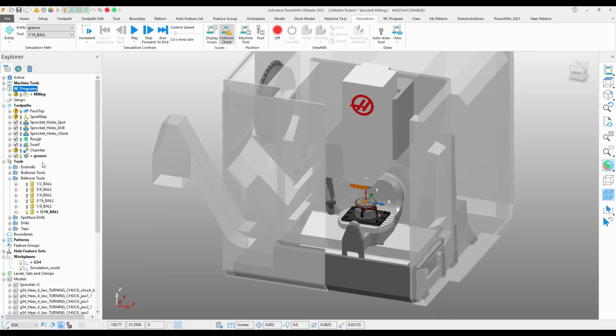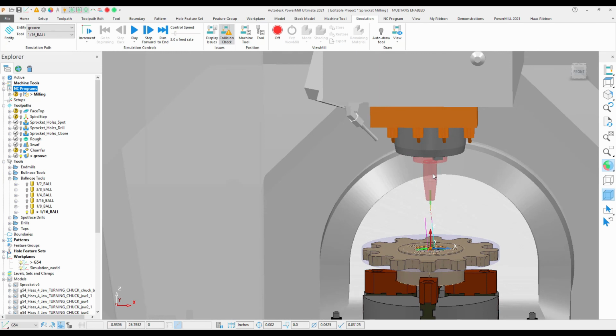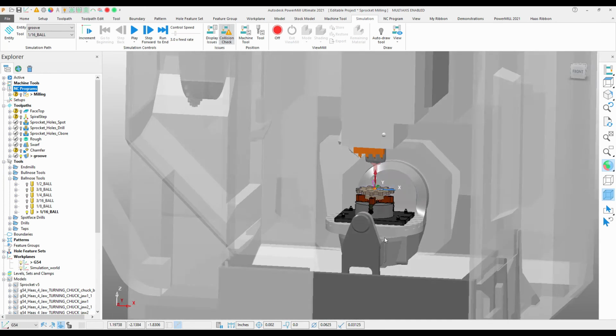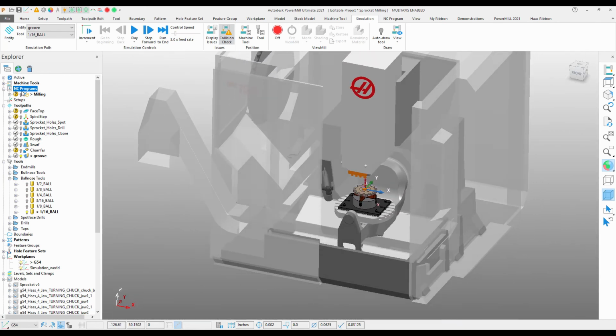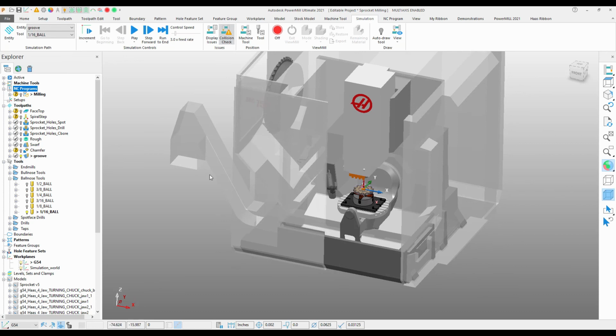There's a few things to be aware of in PowerMill, because when it calculates toolpaths, it gives me these status lights, and these status lights represent safety statuses. So white represents a gouge check against the model. Yellow represents it hasn't really done any checks. So before I run this on the machine, I want to see some nice blue check marks there, which represent that this portion of my tool setup is safe. There are no collisions. And I also want to bring this up to the highest standard, which is an NC verification, which gives me a check that there are no collisions during the machine movements at all. So let's go ahead and do that.